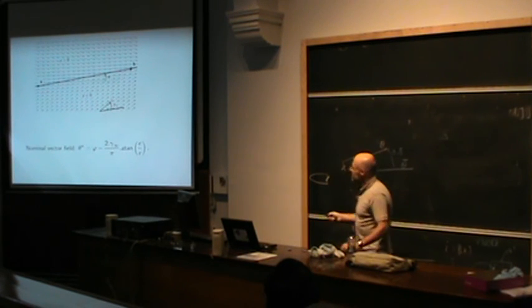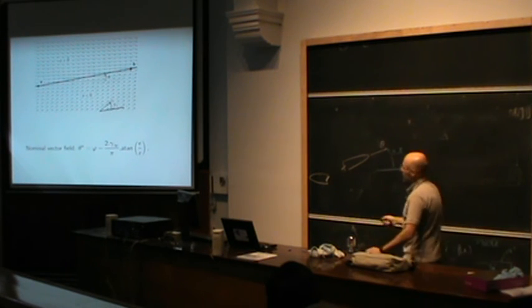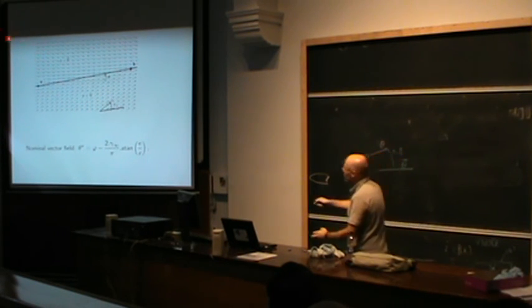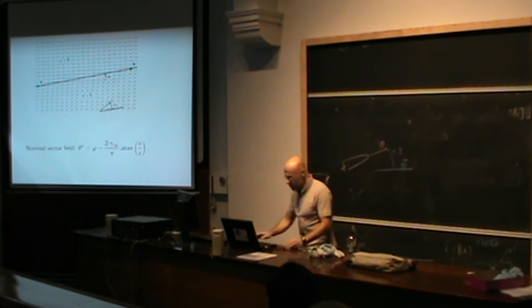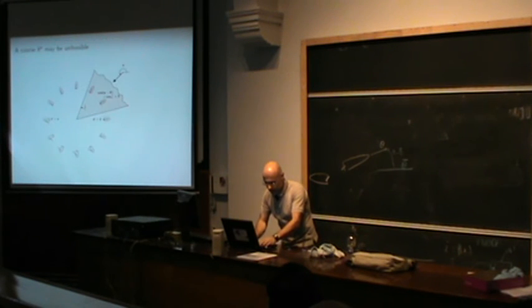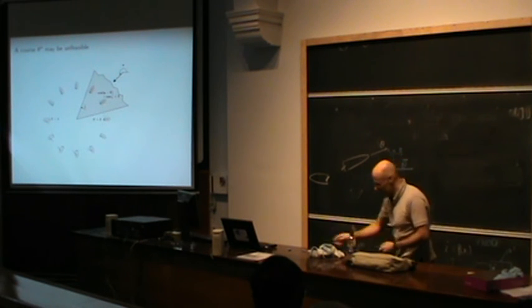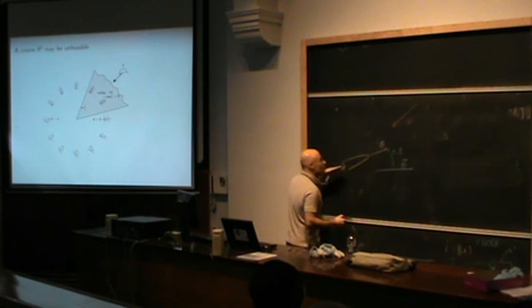So the first step is theta bar, the desired direction. There is a line, and we want to follow the line. When we are here, we ask the boat to go in this direction. When we are here, we ask to go in this direction. Okay. So we have the vector field we want to follow. Now the problem with this vector field is that if the wind comes from this direction, the robot will not be able to go against the wind.